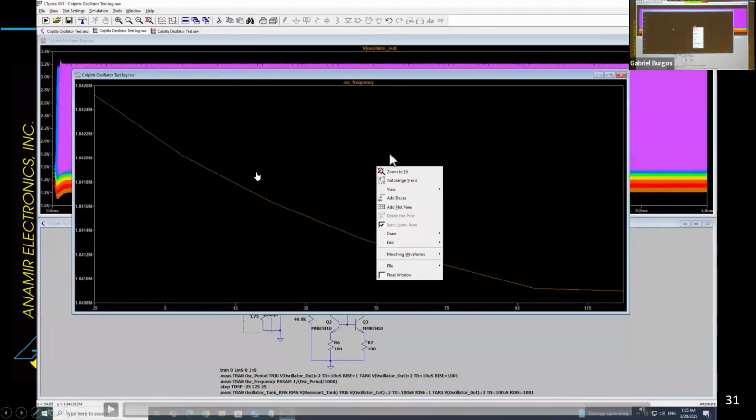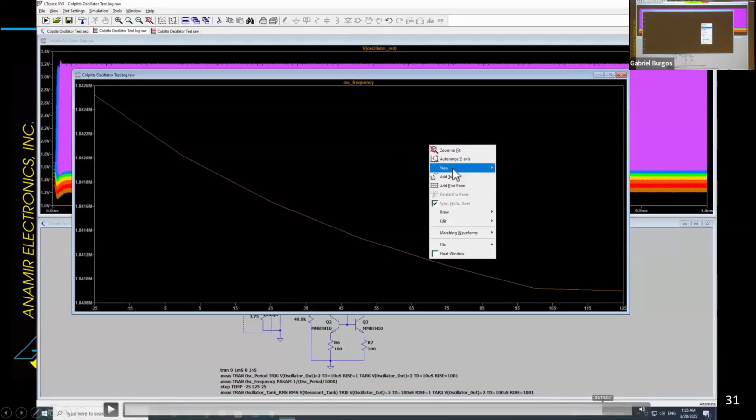And then by just a key click on the mouse, more or less, you can get a graph of temperature versus the oscillation frequency. What I did here. So that's not too bad. I show how I can graphically, using LTSpice's graphical interface, quickly measure how much change in frequency that is. And I have that here somewhere. So it makes it real quick and easy to tell just how good that was.